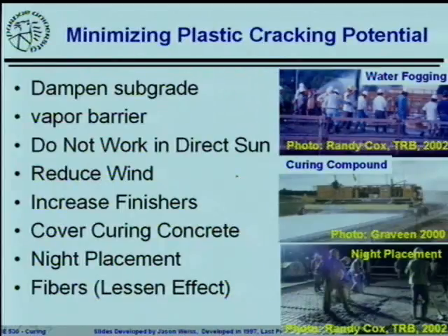I sort of jokingly said it tells you to take caution, but doesn't tell you much of what to do. Here is the list of what you do. Right? Good concrete practice. This was another thing that Menzel was able to do in his paper. He was basically able to describe why good practice is what good practice is. He used that nomograph to show that if you dampen the subgrade, it's less likely for water to leave the system through the subgrade itself. It's more likely for the system to stay wet at the bottom. More water is going to come to the surface. You're going to have more bleed water.